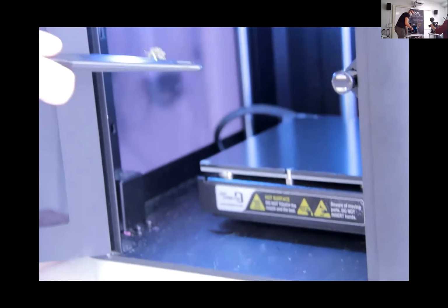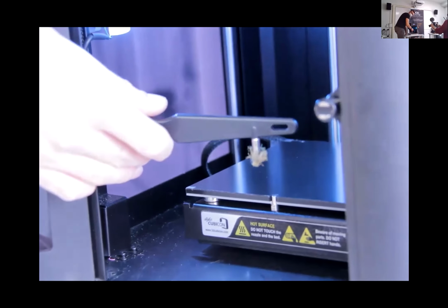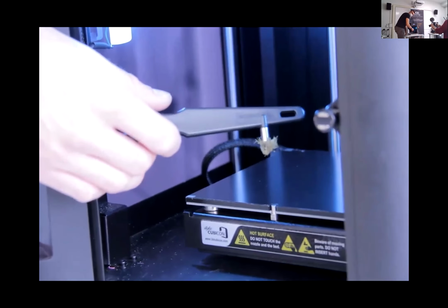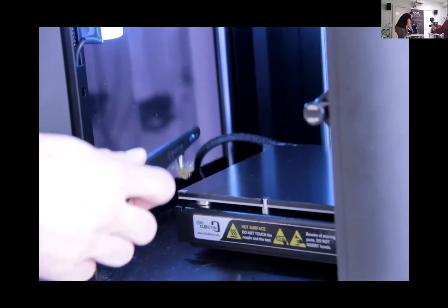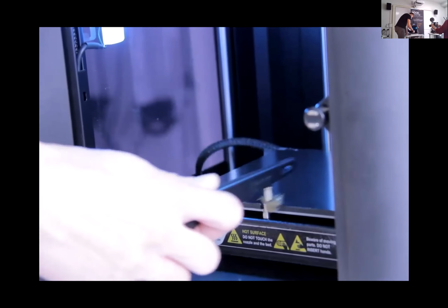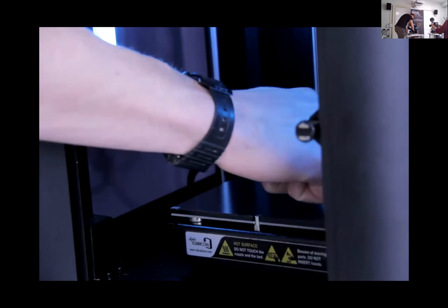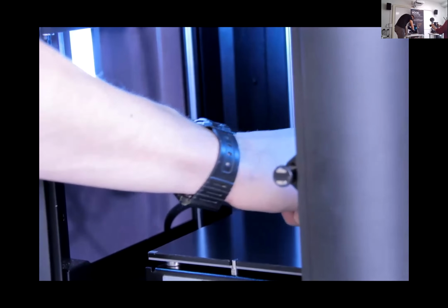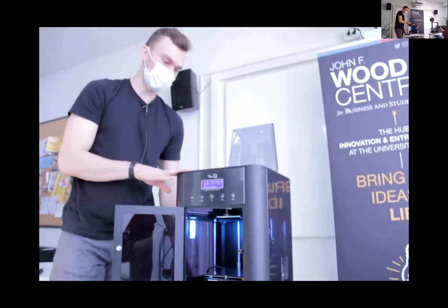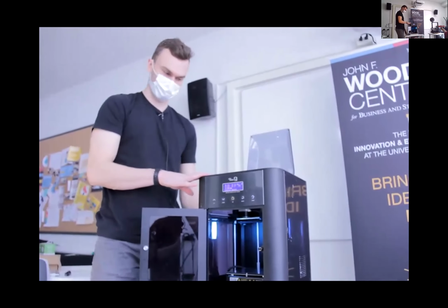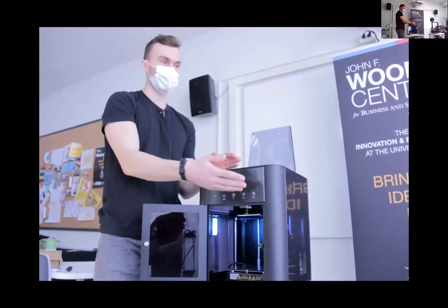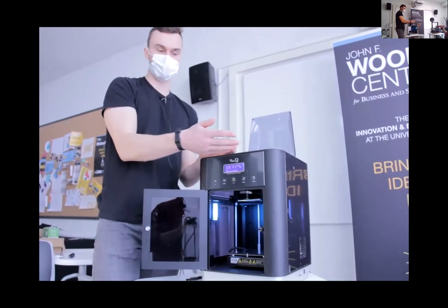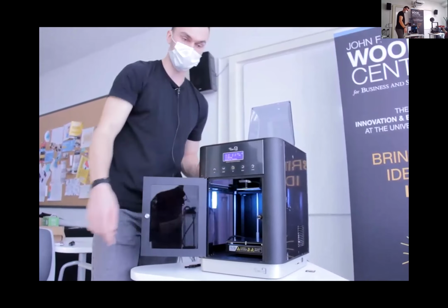But we need to make sure those contacts are clean. So if you haven't used the printer in a while, it's good to take one of these brushes with a little wire mesh brush on the end. And we're just going to brush those contacts off a little bit. And that's just going to make sure there's good conductivity on them. And the nozzle can detect when it's touching them. And that's going to make sure that when the bed levels itself at the start of every print, it's going to be accurate. Okay, so instead of leveling the print bed manually, as we did on the Ender printer, here we just are going to make sure those contacts are clean.